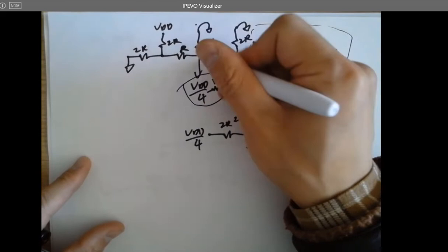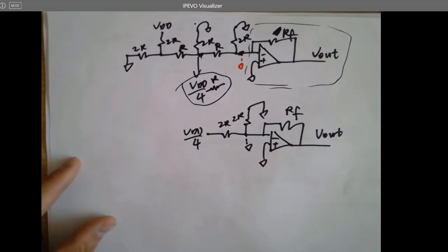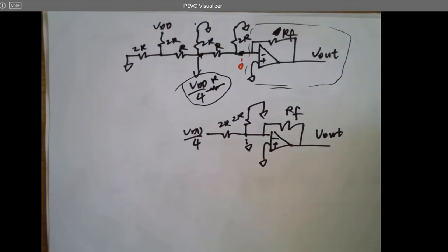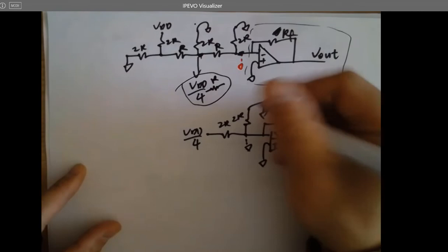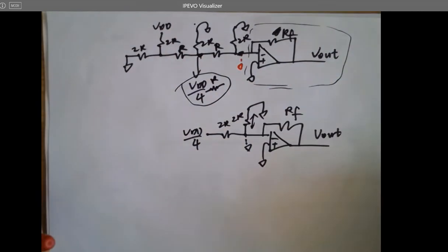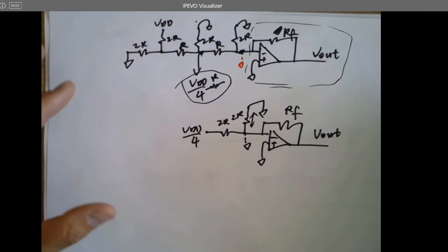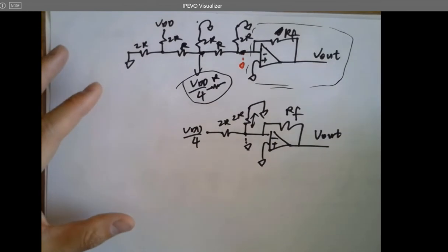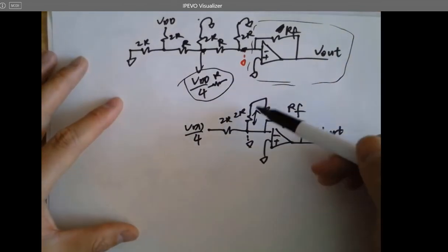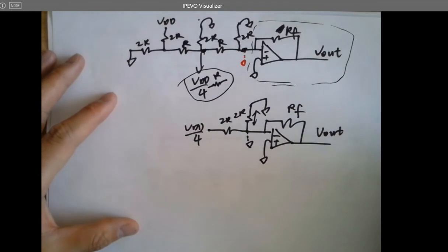That's whatever you want to plug into here, right? So what's going on here? What's the current? 0. Why? No potential drop. This 2R is just holding some space, wasting some space over there. So there's no current flowing through this R, no voltage drop.